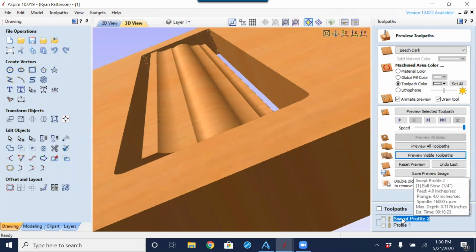And one reason why you might want to do what we just did there, rather than using that 16th inch bit with the tighter step over, is that it's very likely that you could break that bit, especially cutting this kind of depth. Or with that 16th inch bit, we would most certainly have to do a roughing pass to remove all of that material.